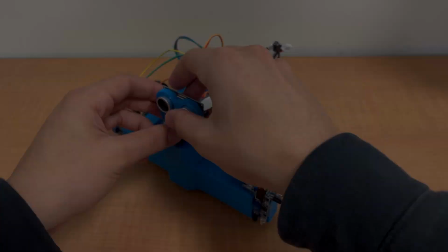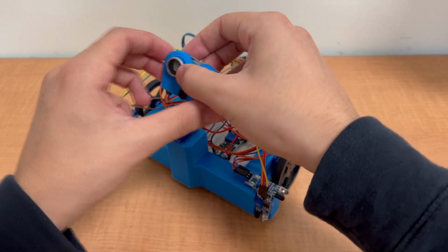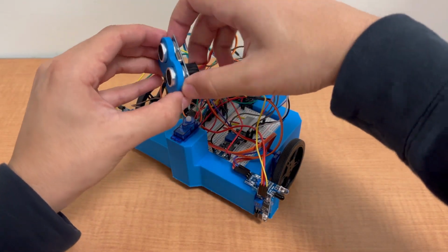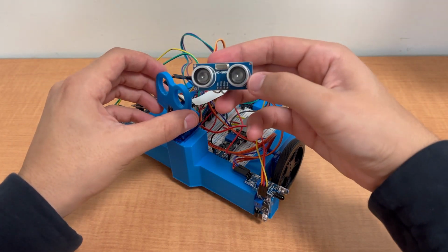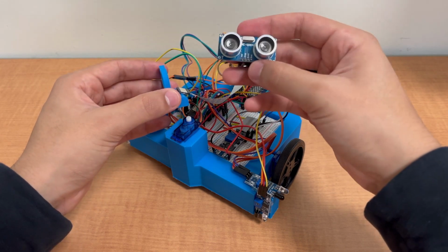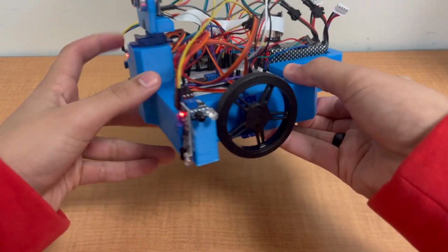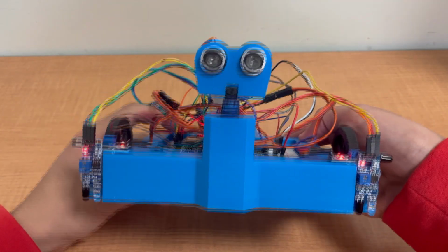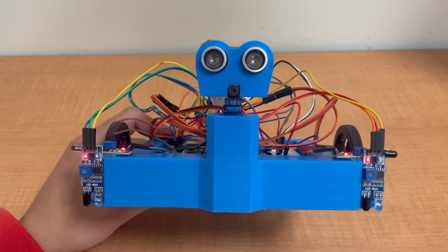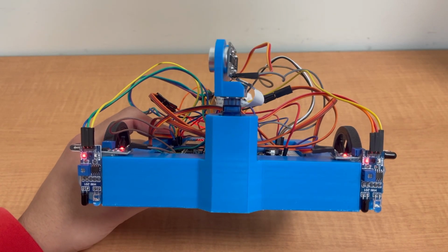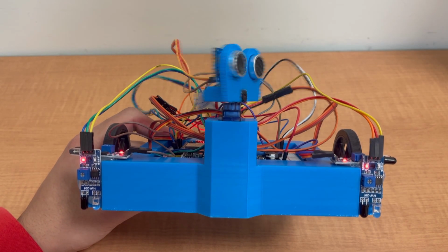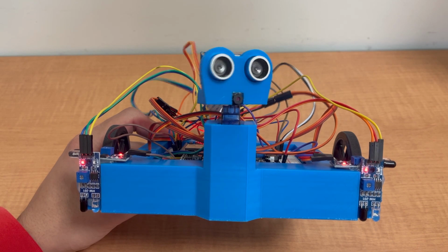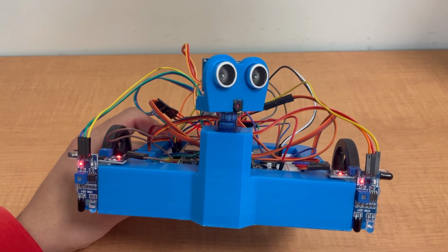Next up, Edward has 1 ultrasonic sensor used to measure the distance from nearby obstacles. The sensor also serves to aesthetically look like his eyes. Next, he has 2 continuous servo motors used to drive his wheels. He also has 1 traditional 180-degree servo motor which serves as his neck to pan the ultrasonic sensor, or eyes, and the extended camera of the ESP32 cam board.